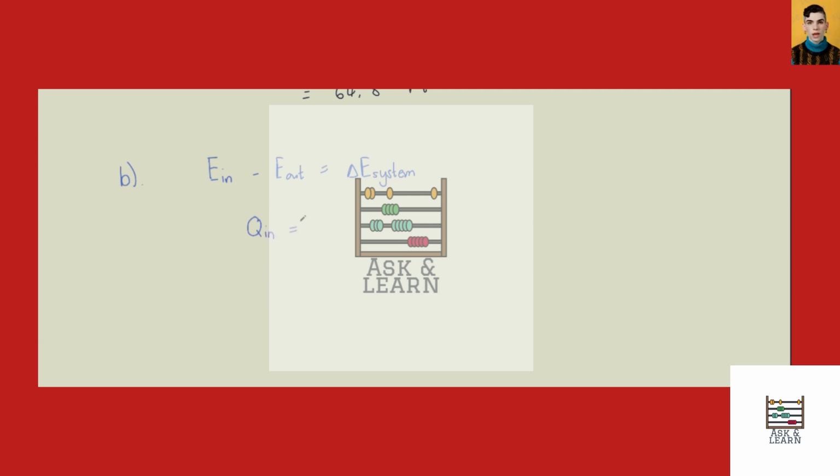So heat transfer Q is in, and this results in a change in internal energy, delta U. Remember, potential and kinetic energies are zero here. So we can write this as the mass of the air times the change in specific internal energies, U2 minus U1. And we can go one further and write this as m times the specific heat capacity for air at constant volume, Cv, times the change in temperature, T2 minus T1.